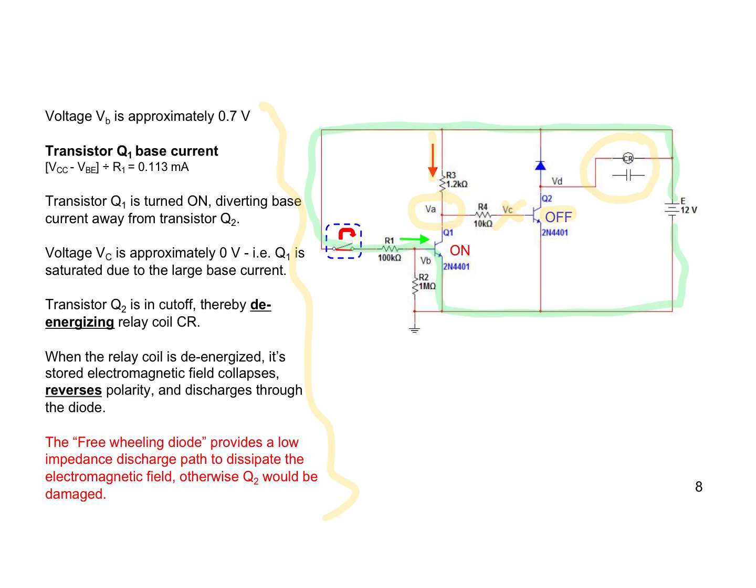Last thing here is that with the freewheeling, this is typically called a freewheeling or a snubber diode. Its purpose there: when we open the switch, as you saw on the previous slide, the coil is going to be energized. When we close it, the coil is going to be cut off.